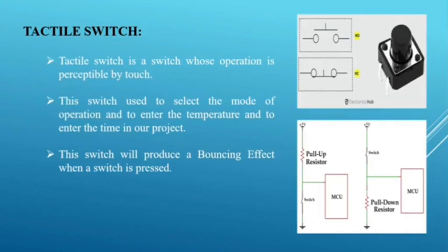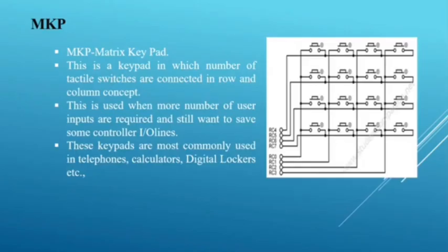Next, tactile switch. A tactile switch is a switch whose operation is perceptible by touch. This switch is used to select the mode of operation, and to enter the temperature and the time into our project. This switch will produce a bouncing effect when the switch is on.